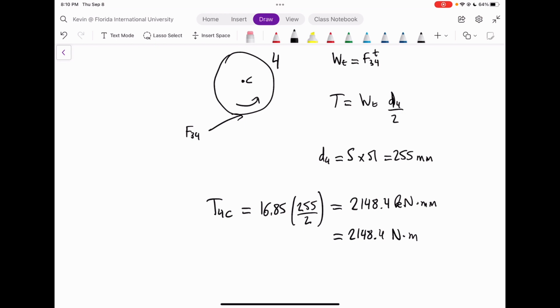So a rule of thumb is, in whichever the direction of the force is going onto a gear that is not being driven, so this gear is being pushed by another gear, it's not being driven at the shaft, okay, like gear 2, we have that the torque from the gear to the shaft is actually in the direction of the force of the gear.